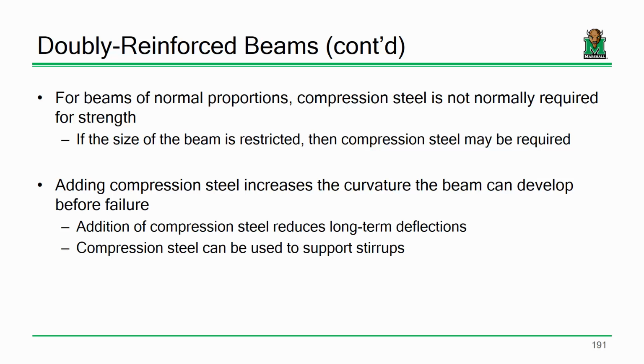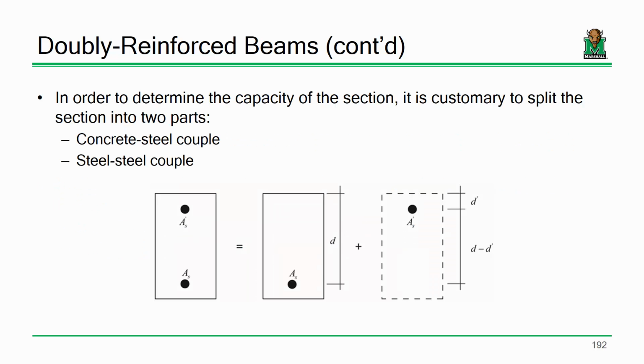But from a design standpoint, you are not allowed to use that full amount of force that you got on day one to compute the strength capacity of that beam. You have to reduce it some. You're only allowed to use something like 85% or 82%, because over time, there's a number of things that cause that force to dissipate. All right. So I went off on a tangent, but at least it was relevant to concrete.